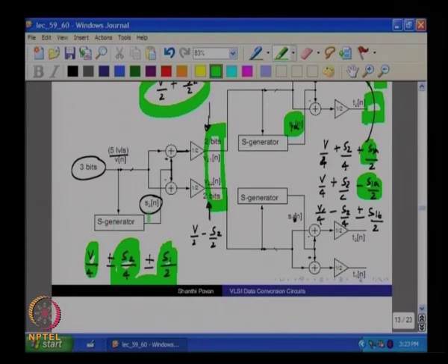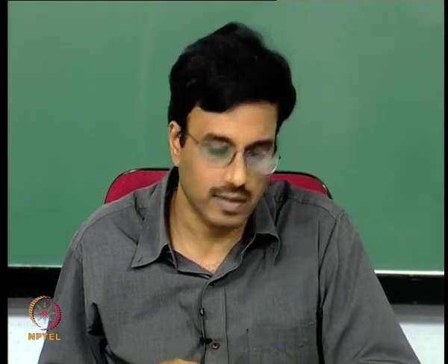If we assume first order noise shaping for S1 and S2, then when there is DAC element mismatch, you will find that the mismatch noise, which was white when we randomized, should now have a first order noise shape, and this should be a huge improvement over pure randomization. Does it make sense?